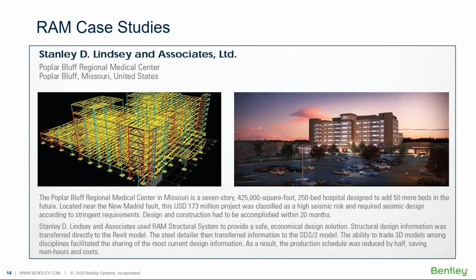for buildings. This way, the engineers have more control in distributing your lateral loads to the lateral framing system. In case of steel buildings, it is the lateral frames with the bracings. In case of concrete buildings, it could be the shear walls that take most of your lateral loads. So this way, when you model a beam or a column or a wall, the program will ask you whether it's a lateral or a gravity member. Okay, depending on whether you choose it as a gravity or lateral member, the color will show as blue or red. Okay.